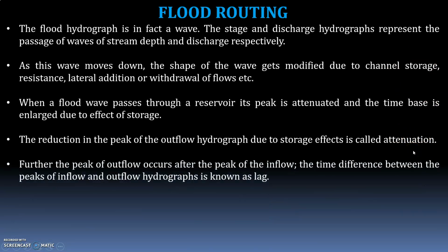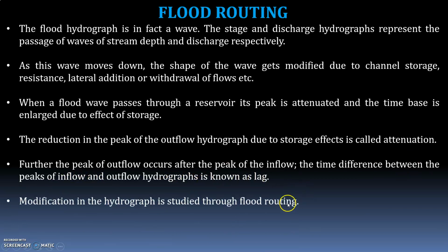Further, the peak of outflow occurs after the peak of the inflow. The time difference between the peaks of inflow and outflow hydrographs is known as lag. Modification in the hydrograph is studied through flood routing.